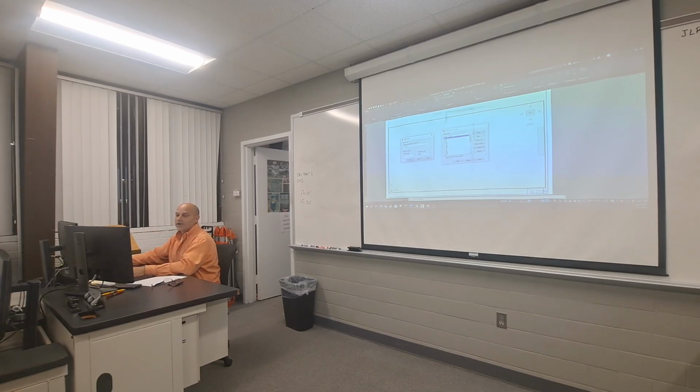All you have to do is go through and type in the name, put the scale factor in the drawing units, pick OK. Add another one, 1 inch equals 20 feet, 20 times 12, 240. You need to do that for all of those scales. So everybody okay with that process?